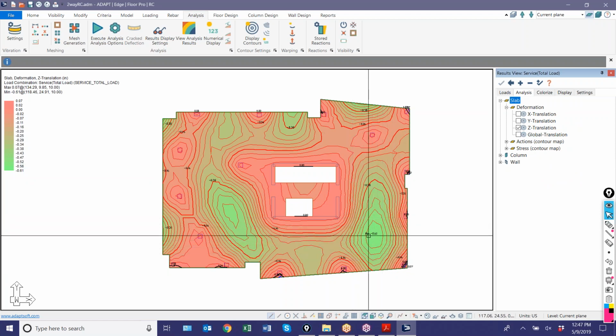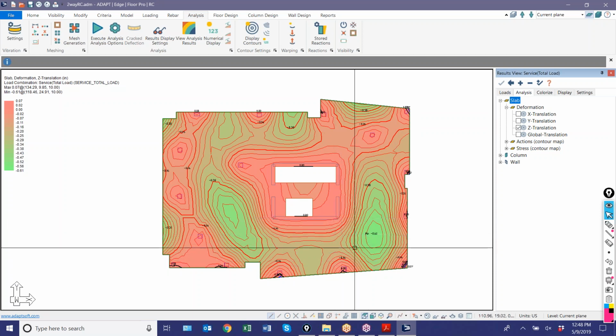It's about 0.61 inches, and maybe our deflection limitation, maybe it's L over 240 or 360, whatever is imposed on the design. And we say, is that going to actually work when we consider long-term deflection and cracking? So based on this particular run, I can't really say whether or not it will work based on those other two factors, but I could determine, maybe if I just do a quick approximation, maybe I multiply this by 3 or 2.5 to predict long-term effect. That's creeping up around 1.5 inches of deflection, maybe even more.